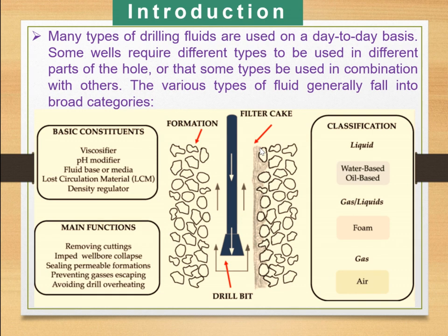Like that, in case of a highly porous permeable formation, there is a possibility of caving or borehole collapse at places. So drilling fluid also makes a certain wall in the form of mud cake. This apparent impervious layer protects against borehole collapse. Other than that, there are so many things which we'll be discussing. So please stay tuned.